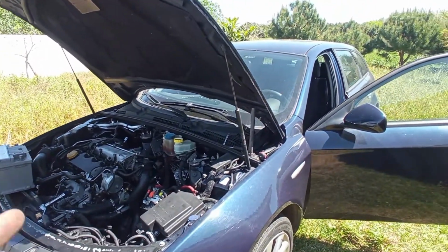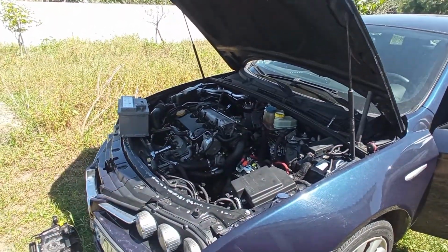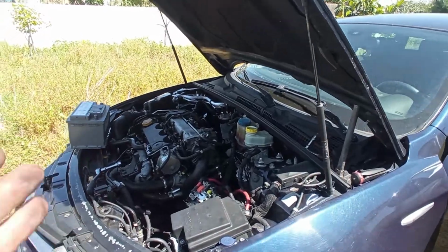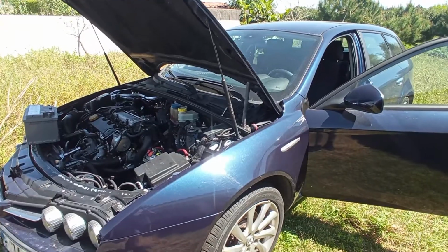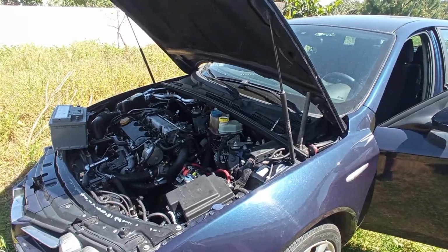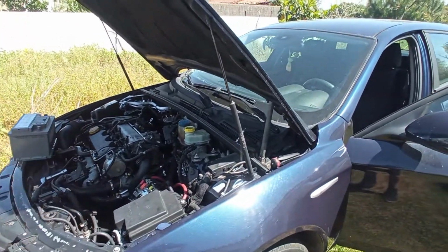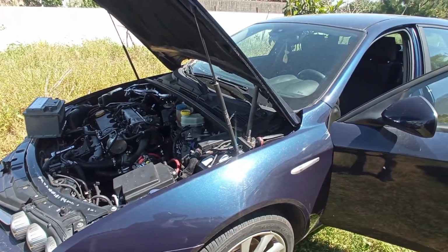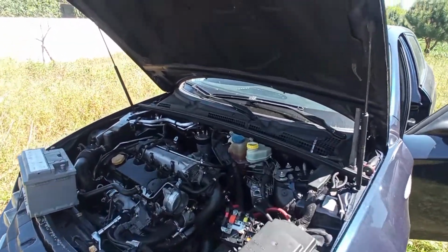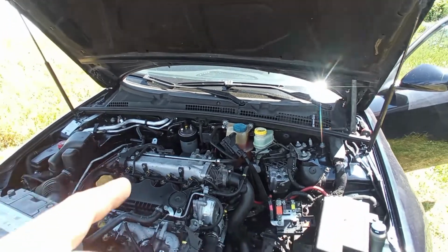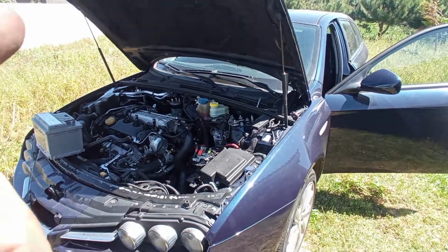I'm pretty sure I will have a higher amount of back pressure at the DPF, because now the exhaust leaks are closed, are solved, and for that I will have a lot more back pressure. And I hope it does, because it means not only that the leaks are fixed, but that the pressure being high means the DPF was really struggling to do its job. And now with a forced regen, I hope to do one. If I'm not able, I have a way to do it without removing it. And I hope that happens, so I can show you how to do it.